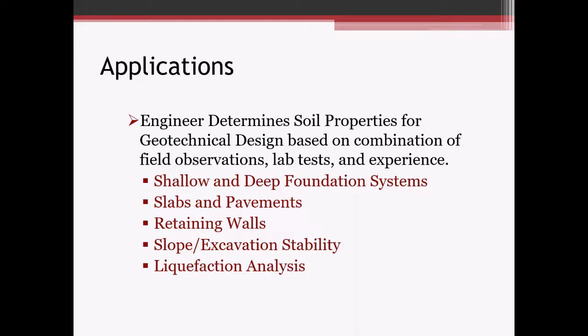Some of the typical aspects we deal with are shallow and deep foundation systems. When it comes to deep foundation systems, the subsurface conditions are usually very poor, and there may be several alternatives that can be evaluated. So engineers are often asked to evaluate the cost as well as the time constraints for each of those alternatives. Slabs and pavements usually involve evaluating soils to shallow depths, typically in the 6 to 10 foot range.